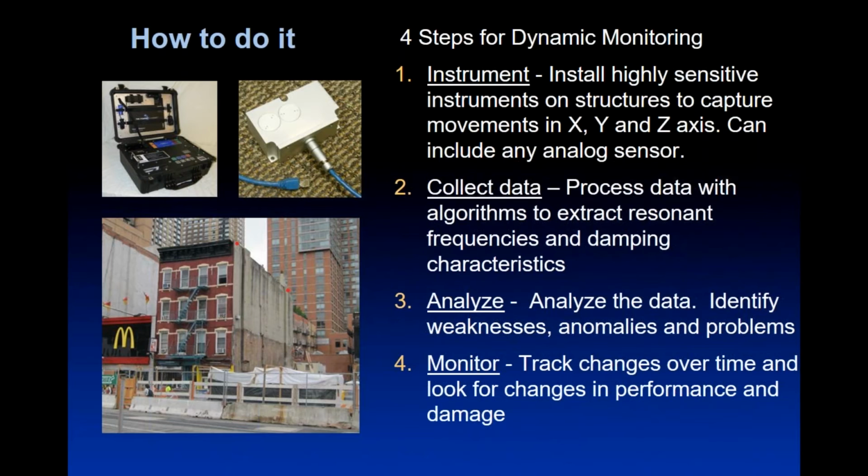Now, displacement, which is expected, you can get from human comfort, from stress levels, or in some codes of practice, they'll tell you what the rules of thumb should be. Like, for instance, h upon 360, which appears in the ASCE 7 code of practice, or the International Building Code in the US.